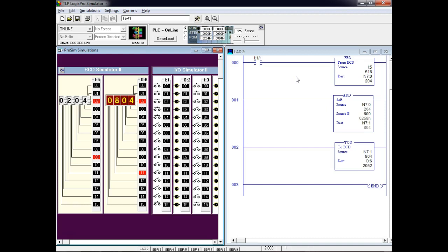We would just start looping, right? And so if I wanted to multiply 10 times 5, then I would make it loop through the addition 5 times, until my multiplier became 0. As soon as my multiplier became 0, how did I know it became 0? Well, I would check that 0 bit in the flag register. And as soon as it became 0, it means my multiplication was what?